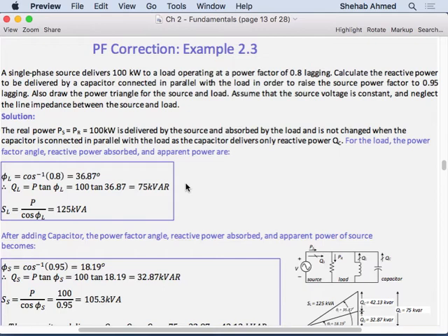So the units for real power are watts. Our units for reactive power are VARs, volt ampere reactive. The unit for complex power is volt amperes, VA. Okay? Any piece of AC equipment is rated in volt amperes. You could not go and tell somebody, I want to buy a 100 kilowatt transformer. They will look at you up and down. Right? You cannot do that. You can tell them, I want a 100 MVA transformer, 100 kVA transformer, right? Because it depends on power factor.